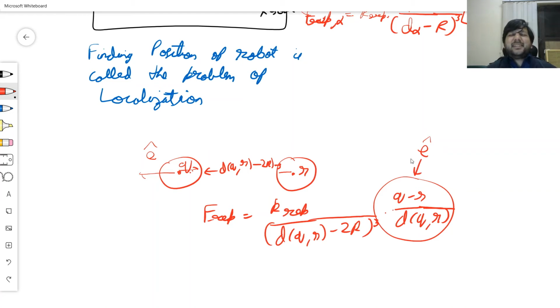It can be calculated without sensing because both robots apparently knew their position and they communicated it to each other. It doesn't mean that if there are n robots, there will be n-square interactions, because every robot will communicate its position to a central master. The central master will calculate the interaction only between the k nearest neighbors, which is a logarithmic-of-n operation using the KD-tree data structure, not discussed over here.